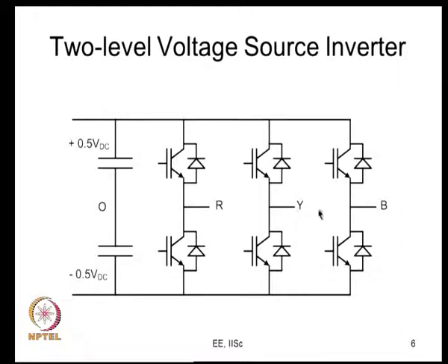The loads are connected, and there will be fundamental and harmonic components also. As you will see, the effect of the harmonic components on the switching loss would be negligible, because the harmonic currents themselves might be negligible compared to the fundamental current when you are switching at fairly high frequencies, and of course, switching loss is mainly a concern at high switching frequencies. This is the load, and this is the DC side, and the DC source is connected there, and how much DC link current and capacitor current flows we had seen previously in an earlier module.